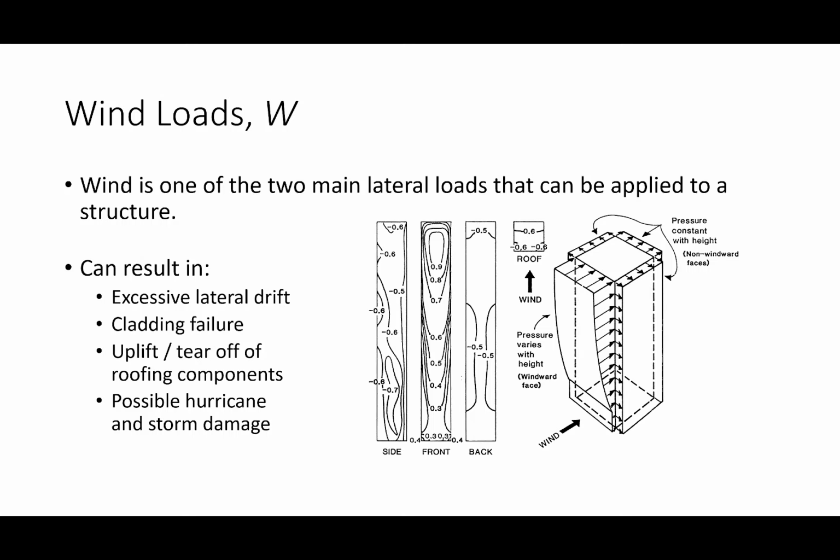Wind is one of those things that varies as a function of height, and the taller a building gets, the bigger your wind forces are. The example I like to use is if you've ever been on top of the Empire State Building, the observation deck on the Empire State. If you ever go up there, it's really windy. The higher a building gets, the larger the wind forces are. In fact, it's kind of parabolic in nature.